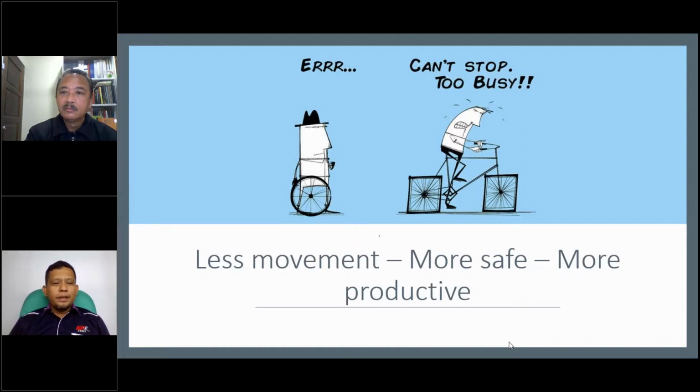Pipe is one of the common solutions because it can reduce the movement of tankers, for example, that use a driver. The pipes can charge the chemical straight to the reactor, and we can use the control room, so it minimizes people interaction. But if you use forklifts, tanks, manual pumps and so on, it is more hazardous.